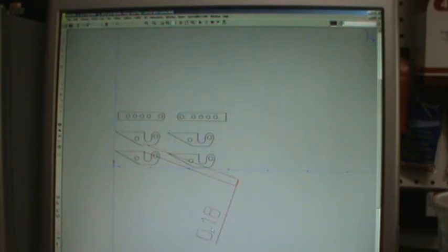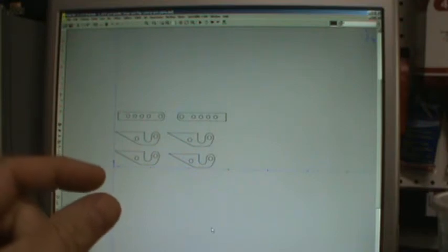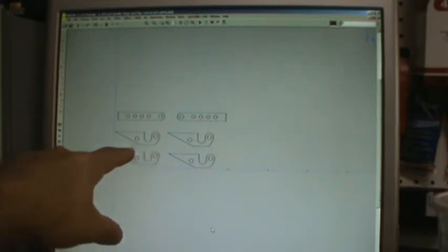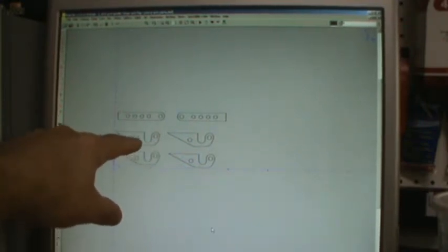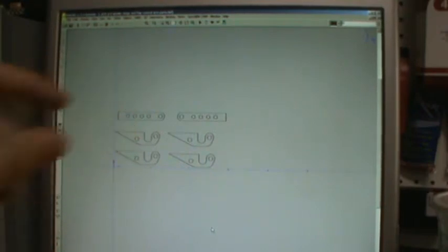And the reason why I say about 1/8 of an inch clearance is because with a 16th inch bit, by the time you route around this way and you route around this way, that 16th of an inch is going to be pretty close to cutting out of each other. So you want them close but not too close. That way when you go to cut this part out, you don't actually end up cutting into this one and vice versa. So on those will be good.